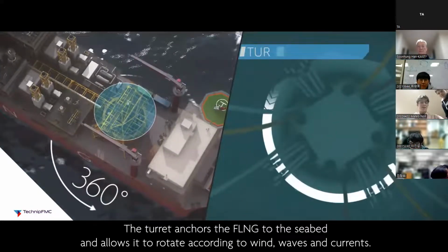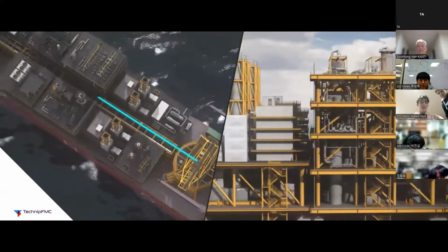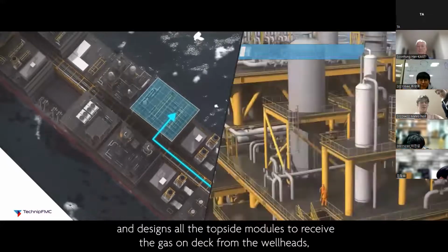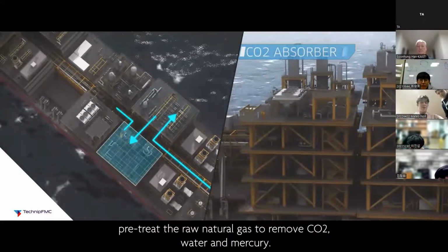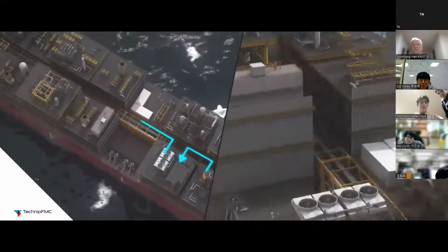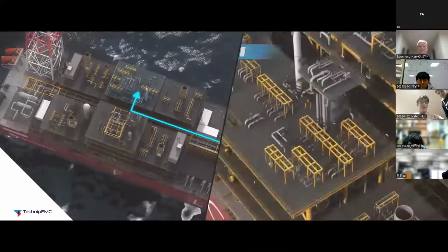The turret anchors the FLNG to the seabed and allows it to rotate according to wind, waves, and currents. From the composition of the feed gas, TechnipFMC develops the optimum process and designs all the topside modules to receive the gas on deck from the wellheads, pre-treat the raw natural gas to remove CO2, water, and mercury. NGL is also removed with co-production of LPG and condensate when the gas is rich.